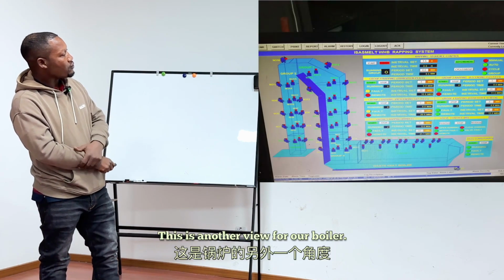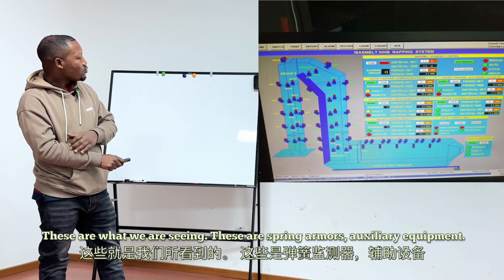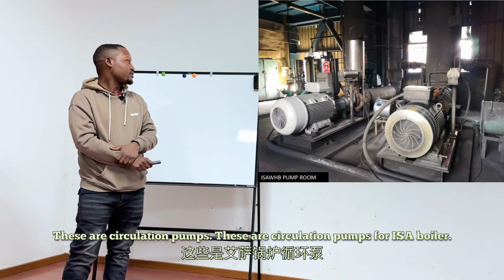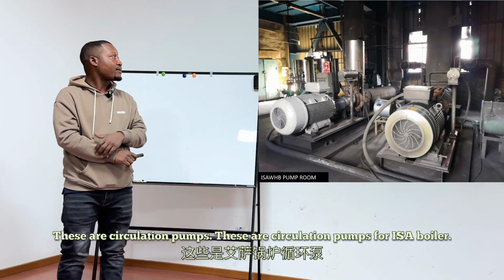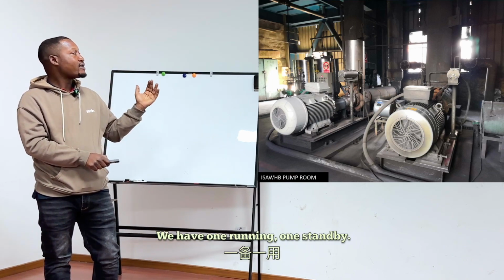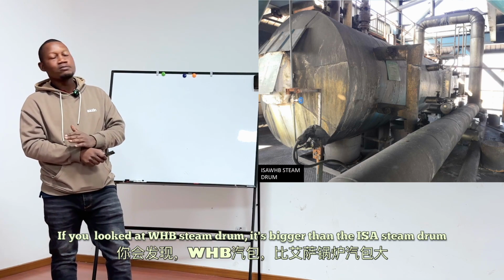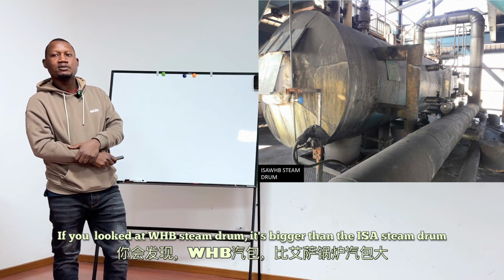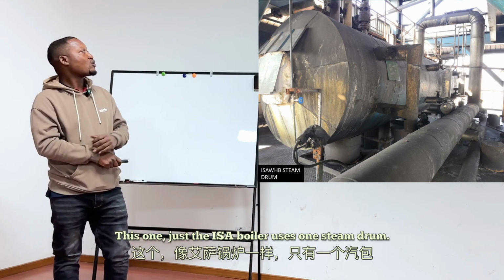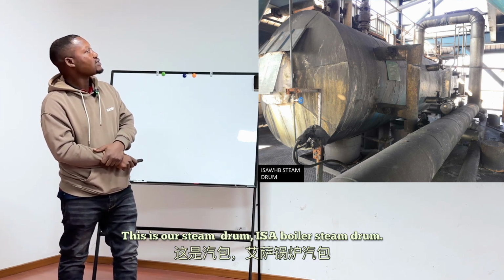This is another view of our boiler. We have the ascending chamber, descending chamber, horizontal chamber. What we are seeing are spring hammers, auxiliary equipment. These are circulation pumps for the ISA boiler. Like I said before, very important equipment. We have one running, one standby. Then this is our steam drum. The CWHB steam drum is bigger than the ISA steam drum because five CWHB boilers connect to one steam drum. For the ISA boiler, just one boiler uses one steam drum. So this is our ISA boiler steam drum.